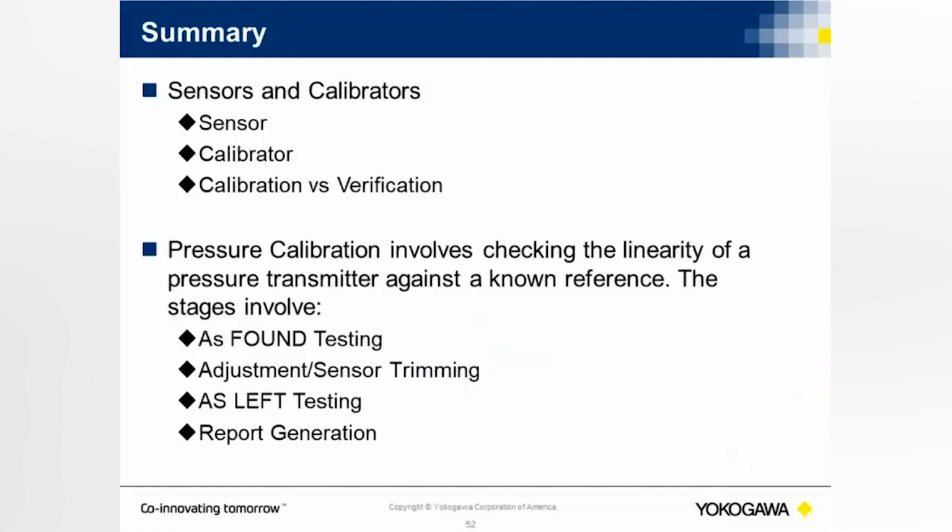We then touched upon sensors and calibrators. So sensors are devices that output voltage, current, or resistance in proportion to measured phenomena such as temperature or pressure. Calibrators have the same features but take this one step further by being able to source these same signals to be able to check the health and validation of sensors. They're generally 3 to 4 times as accurate in their sensing technology.